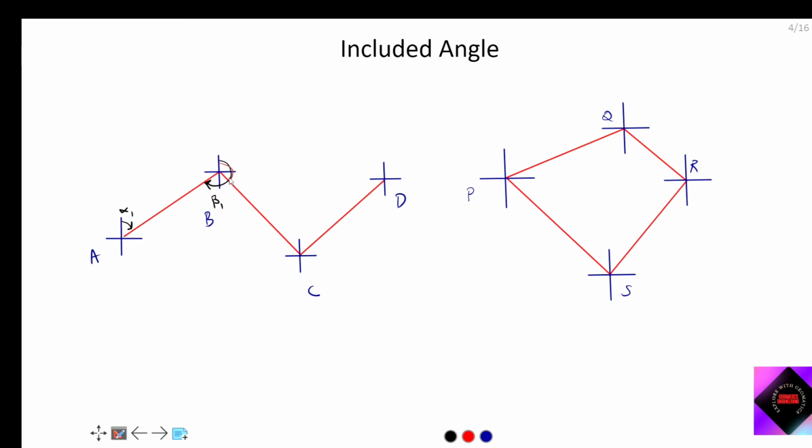So this one will be like this, from here to this. You now know how to measure forebearing and back bearing. If nothing is given, just use the whole circle bearing system, it is very good, and do the calculation in this way: from north, this one is our north, this one is our south.